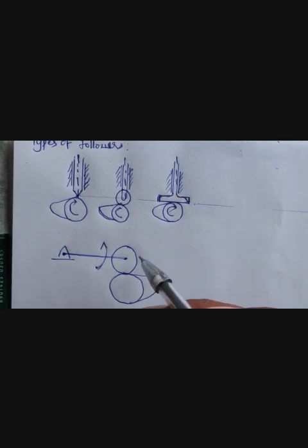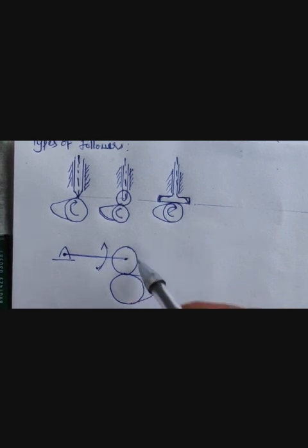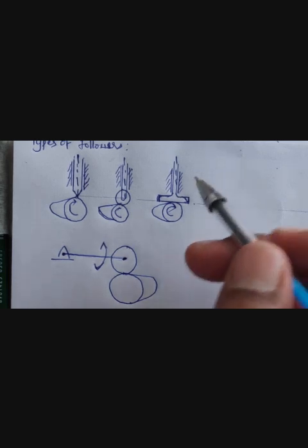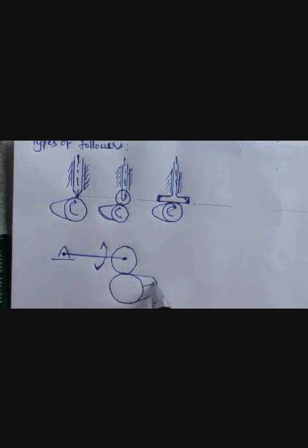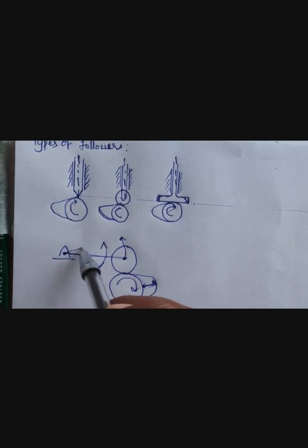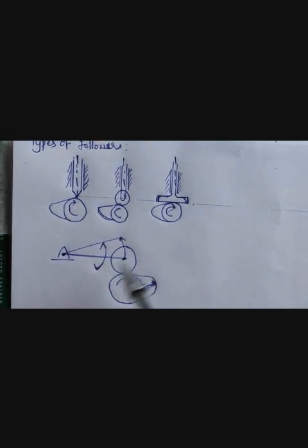In our syllabus and in most engineering colleges' syllabus, we have the roller attached to the end of the oscillating follower. Here you see that each time the cam revolves like this, the oscillating follower would be lifted through an angle.